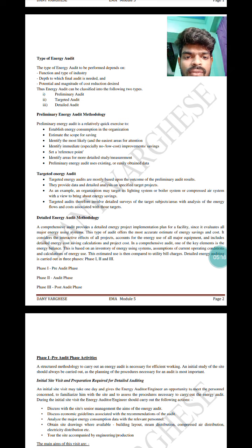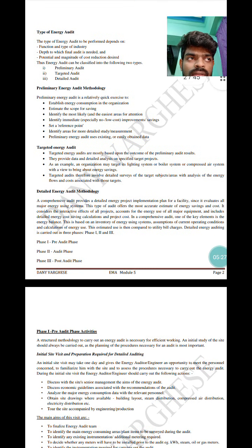plan for a facility since it evaluates all major energy using systems. This type of audit offers the most accurate estimate of energy saving and cost. It considers the interactive effects of all the projects, accounts for the energy use of major equipment, and includes detailed energy cost saving calculations and project cost.